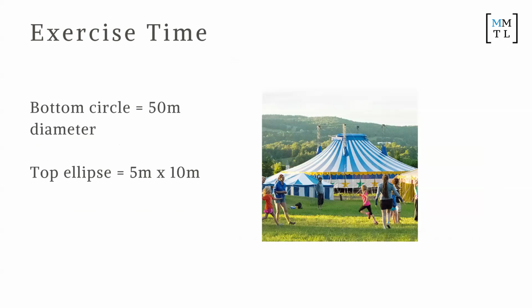The height, let's do 15 millimeters of height. So offset the next plane by 15 millimeters, because it has to hover above it. The loft is creating two different sketch profiles of different size. The computer does that. So we're learning a new function that connects them. You need to create a new plane and create a different shape on the top plane. You can do any shape really. How high above? 15 millimeters.